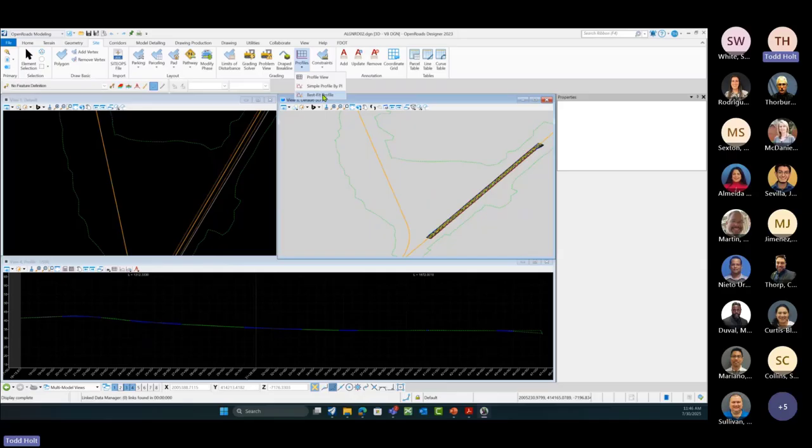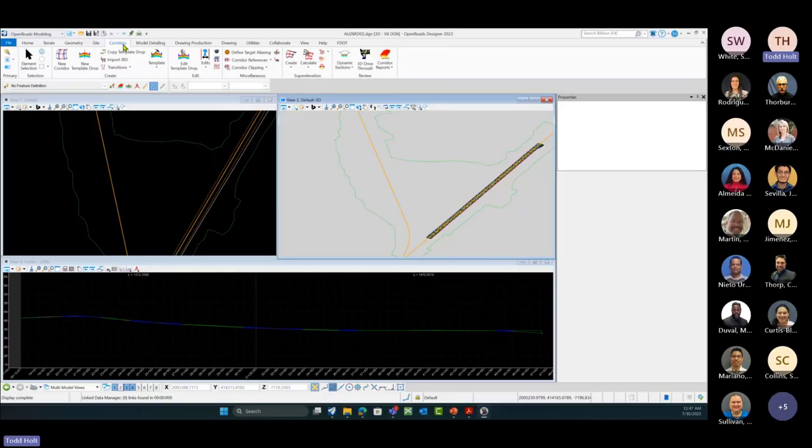These tools, I like them a little bit better than the corridor tab's tools for this, the overlay vertical adjustment tool. And the reason is that if you use this tool, it's going to run through and create the PIs. So it's going to create a chopped up profile, which we'd have to probably create a best fit profile off of anyway. So it'd be an extra step. But this is another option that we could use that will run through these tools as well.